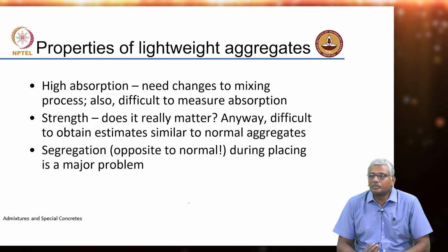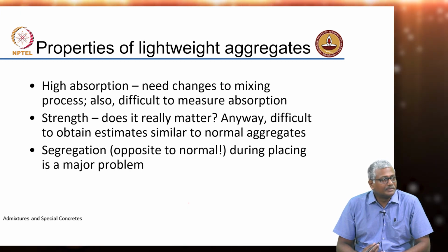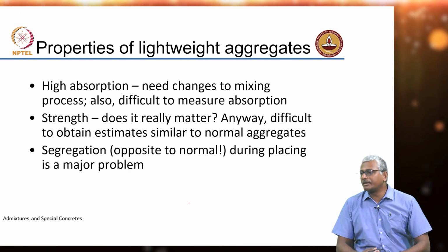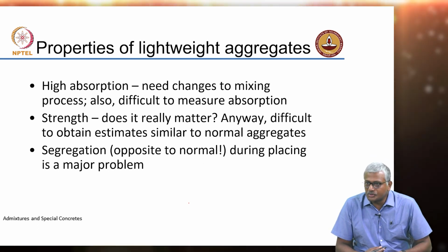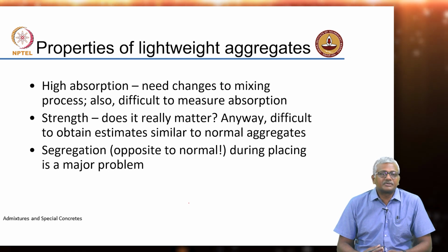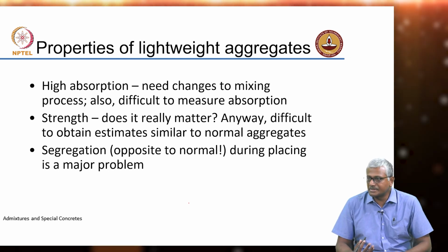Will the aggregate come into picture? Yes or no? No, right? Because in low strength concrete, the cracks pass through the ITZ. When you make the concrete stronger and stronger, the ITZ becomes strengthened, and then the cracks can pass right through the aggregate. We discussed this, right?